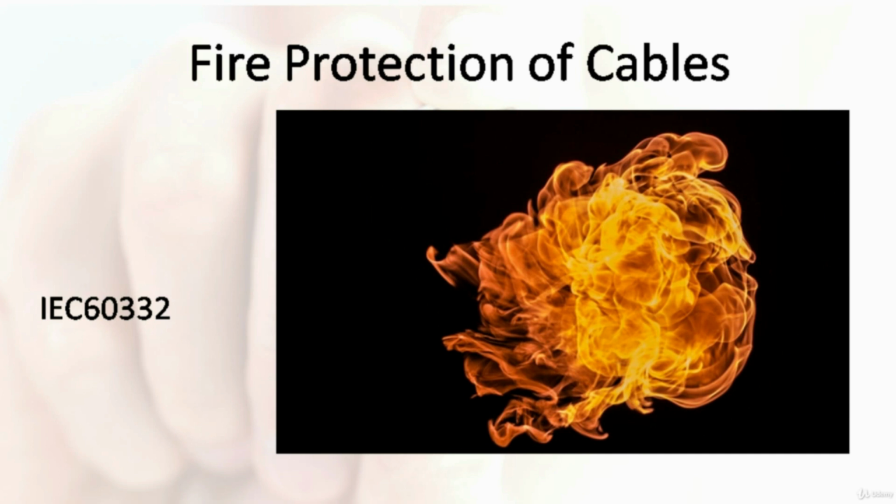One area within your facility that you need to pay extra attention to is the plenum space, which is the space that is used for the air circulation system. This area carries airflow between the interior of the facility and the outside environment, which makes fire easily spread in this area.